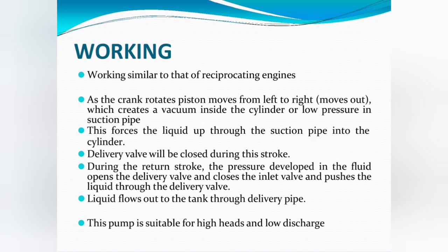During the return stroke, the pressure developed in the fluid opens the delivery valve and closes the inlet valve and pushes the liquid through the delivery valve. Liquid flows out to the tank through delivery pipe. The pump is suitable for high heads and low discharge uses.